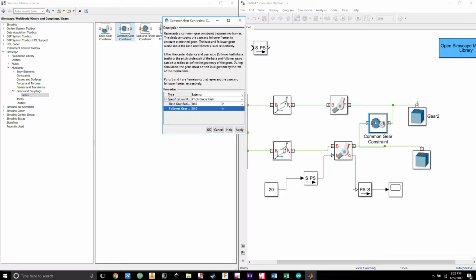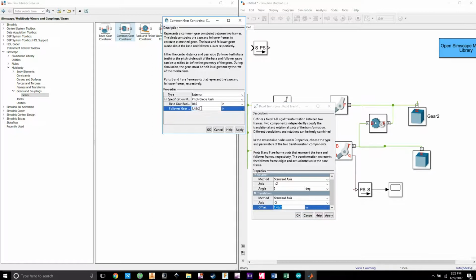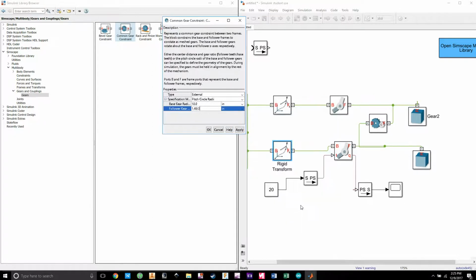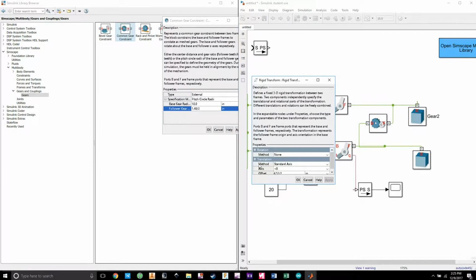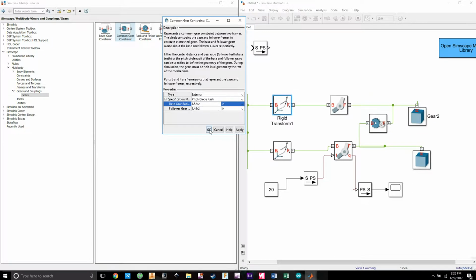So if I go to my transform and remember how far I translated it over, which was the radius of it, I'll copy that number, Control C, and then paste that number into here, Control V. And then the radius of the follower, let's go to how I translated by 4.52 divided by 2, which was the radius. So copy that by holding down Control C and then pasting that in here, Control V. And the units were inches, and I hit apply.